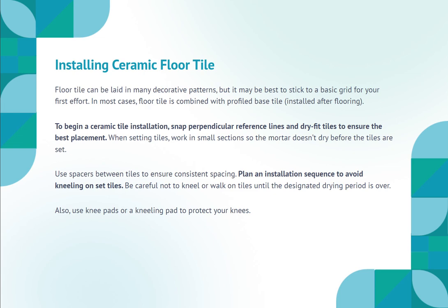Plan an installation sequence to avoid kneeling on set tiles. Be careful not to kneel or walk on tiles until the designated drying period is over. Also, use knee pads or a kneeling pad to protect your knees.